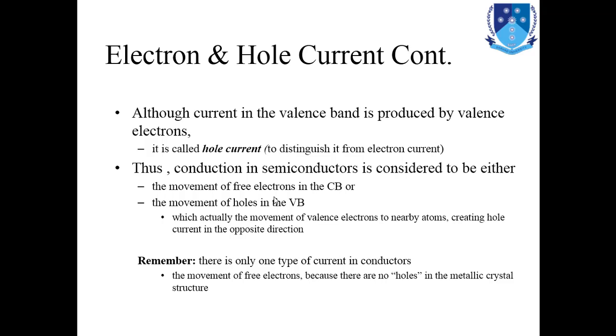Thus, conduction in a semiconductor is considered to be either the movement of free electrons in the conduction band, which is termed electron current, or the movement of holes in the valence band, which is termed hole current.